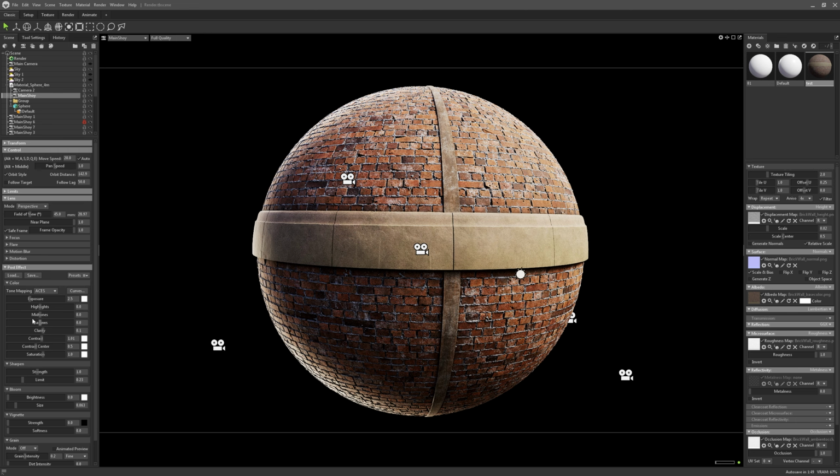and I'm gonna go to the post effects because this is where things get interesting. I'm using a tone mapping of ACES with an exposure of 2.5. Then I'm using a 0.1 clarity and a contrast of 1.01. The contrast center is 0.5 and a saturation of 1. Now the really important part that you can see here is the curve. What I'm doing is leveling some parts on the right side of my curve to the top side and lowering some left side of my curve into the lower part. This is going to allow me higher contrast in my material.